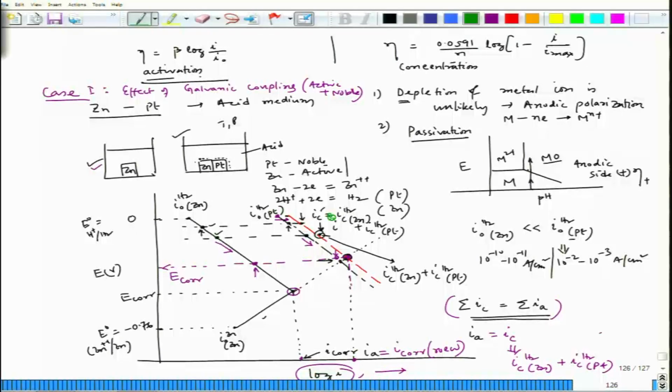So, again, if I follow the same way as we have done in case of platinum, this one would be the new mixed potential, and we could see that the corrosion current density has gone up. This line indicates the addition of the current density following this polarization of hydrogen evolution on zinc surface, and hydrogen evolution on platinized platinum following this particular arrowhead, the green arrowhead.